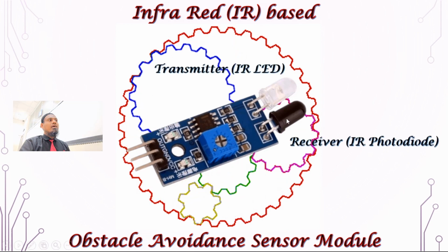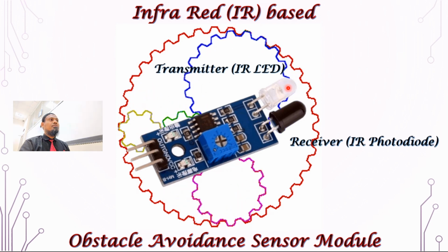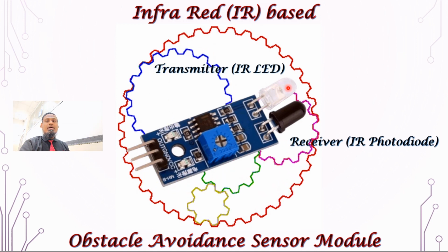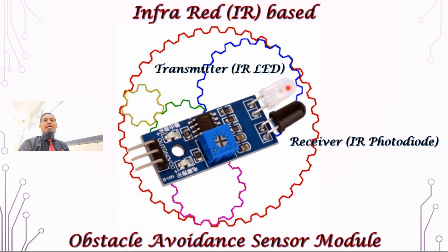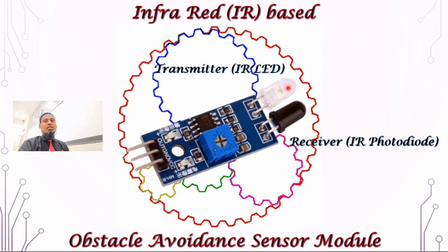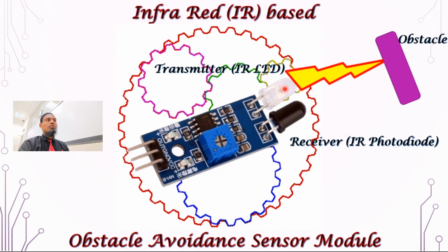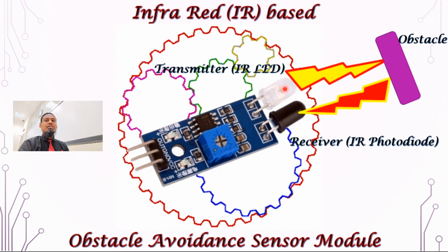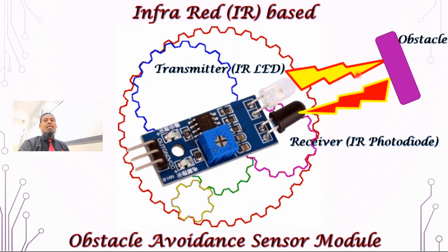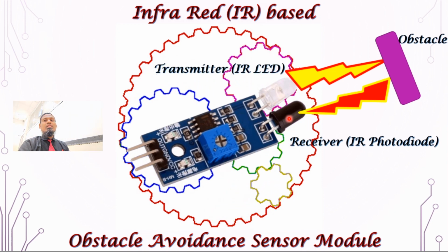There is a transmitter and a receiver. The transmitter will emit IR light, and if it is not finding any obstacle in the visibility of this sensor, it will not be reflected back at all. So when the transmitted light ray is not reflected back, by default the output of this sensor will be 1. If an obstacle is in the visibility of the sensor, the transmitted IR light will fall on the obstacle and be reflected back. It will be received by the receiver of this module, and when the receiver collects the transmitted IR ray, the output will go low. So depending on these two conditions, we are going to control the electric motor.